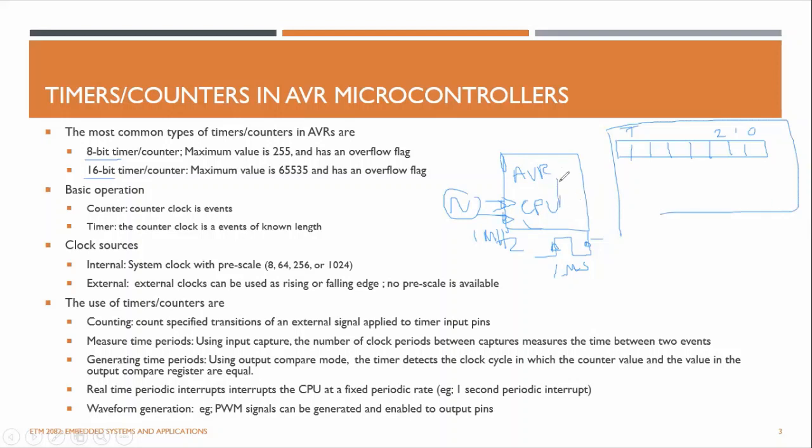It is inside the AVR, but it is dedicated hardware for that. So it needs a clock source to generate this pulse, right? If you can use this oscillator frequency available to the CPU, then for every clock cycle, you can update this 8-bit register. Like if this is here, it will count as 1.